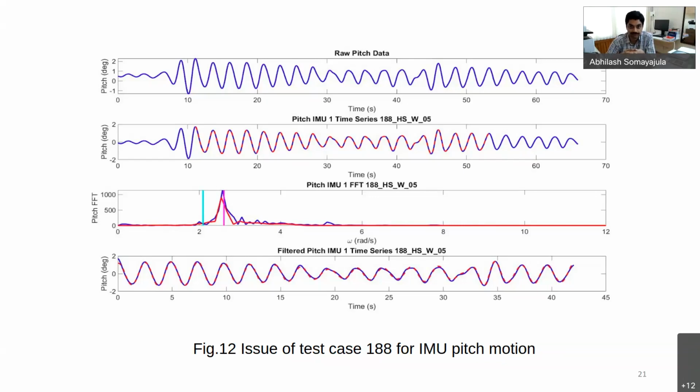That will separately lead to accumulation. The moment you start integrating, you will create a drift and a linear variation as well, which you will have to account for again. But this way, you can directly compute it from the acceleration, and you know that it should be minus omega square times the amplitude. So it might be a better way to do it.